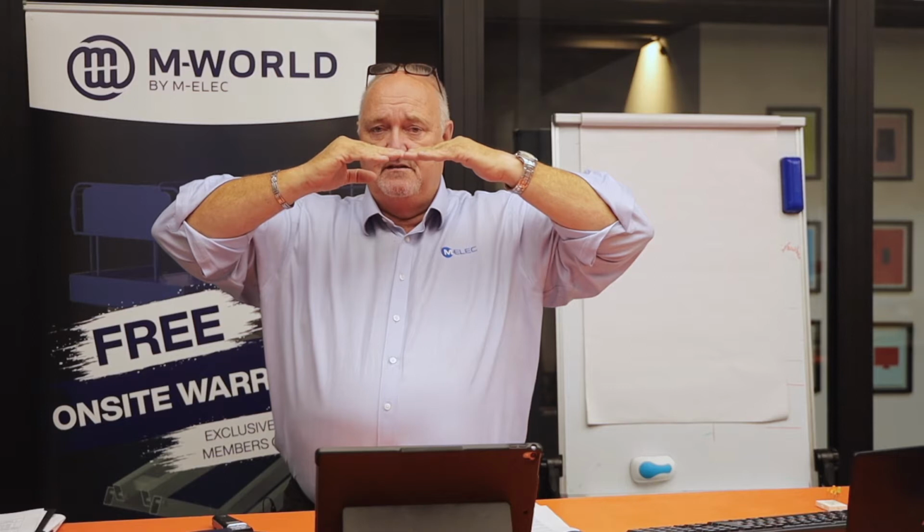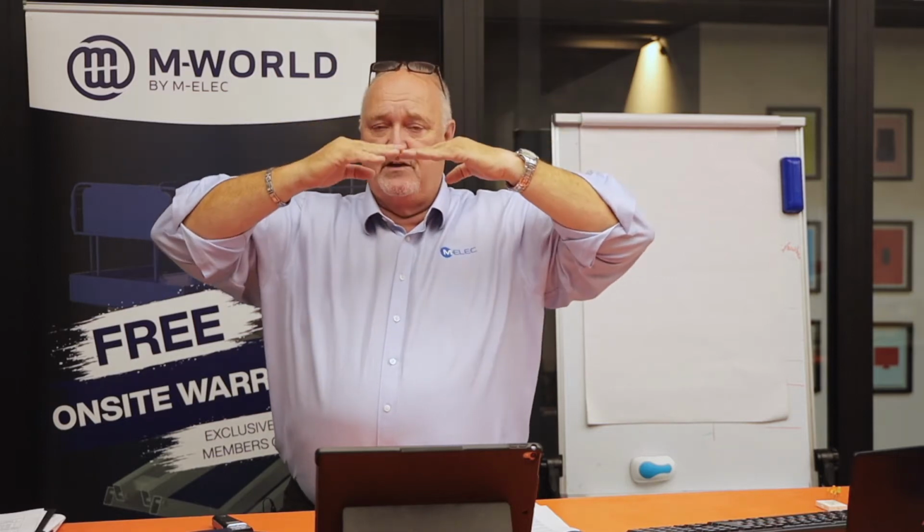Now, when we look at LED lighting, it's not the LEDs that fail. It's the componentry that's attached to the LED that fails. So the easiest way is we do a workshop or a factory test. Once the light level drops to 70%, from 100% to 70%, that's the life expectancy.